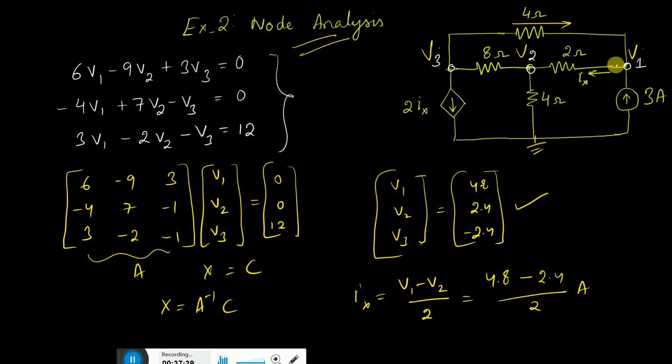So in a network you need to find how many nodes are possible, get the minimum number of nodes, and the node which is connected with the maximum number of branches, make it the reference. In the book, to create confusion, they can also say this node 2 is the reference one, they can make this a node 2. In that case you can take it as an exercise and solve it. Like if this is the reference, then how are you going to solve it?